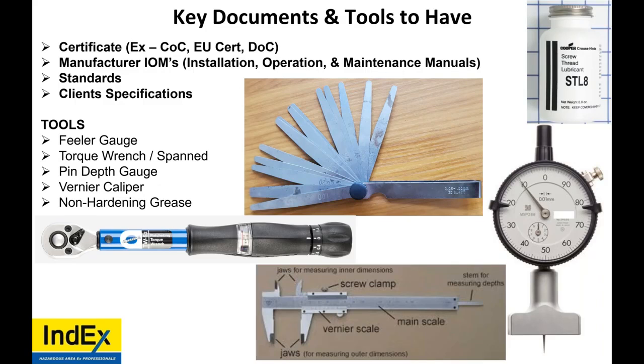Is there a difference between the longitudinal and parallel scratches of a flange? Yes, absolutely. If the scratch goes across the flame path, that is the most dangerous because then the gas can get out along that path. There are assumptions as to what percentage across is okay. Some people say 10%, some people say 20%. But how deep is that? Well, I would use the pin depth gauge.